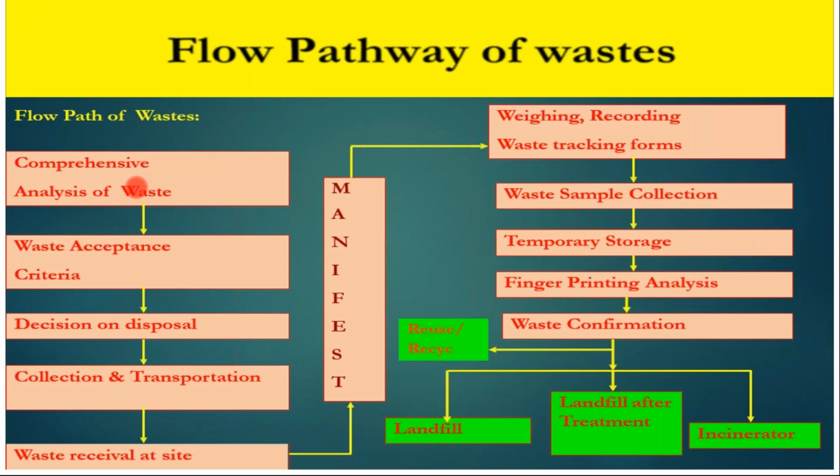This is the comprehensive analysis of waste, then waste acceptance criteria, decision on disposal, collection and transportation, waste retrieval at site, manifest, weighing and recording of this waste, waste tracking forms, waste sample collection, temporary storage, fingerprinting analysis, that is FPA facility, then waste confirmation, then whether it is reusable, recyclable waste, or should be sent to landfilling, whether landfill after treatment is required or not, or whether this waste is only for incineration purpose.